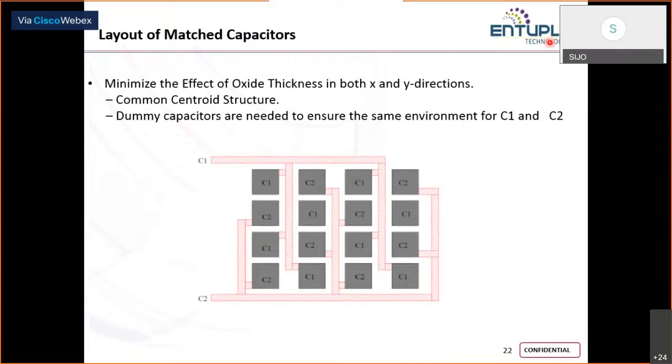Okay, or in the worst case we'll be going for linear ones. Always we will try to have a better aspect ratio. So in that case, it is better to instantiate unit capacitors, divide your huge capacitor into unit capacitors, and make use of your common-centroid structure, dummy capacitors, and interdigitization for better matching between C and F. That is what I have shown here. We will be showing the same thing in the op-amp layout for the compensation capacitor also.